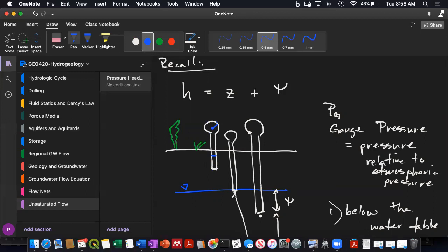What would happen is that, remember we talked about capillarity, how the water adheres to the soil and gets pulled into those capillary tubes. So if I stuck this thing and it was sealed at the top and it had water in it, water would get pulled out by the capillary action. All right, we talked about that. That's the cohesion of the water to the sediment walls and to itself, and it tends to pull things up those tubes.